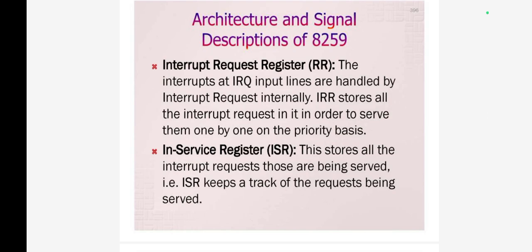Interrupt request register, shortly IRR. The interrupts at the IRQ input lines are handled by the interrupt request register internally. IRR stores all the interrupt requests in order to serve them one by one on a priority basis. The interrupt request register has 8 bits, from IR0 to IR7.